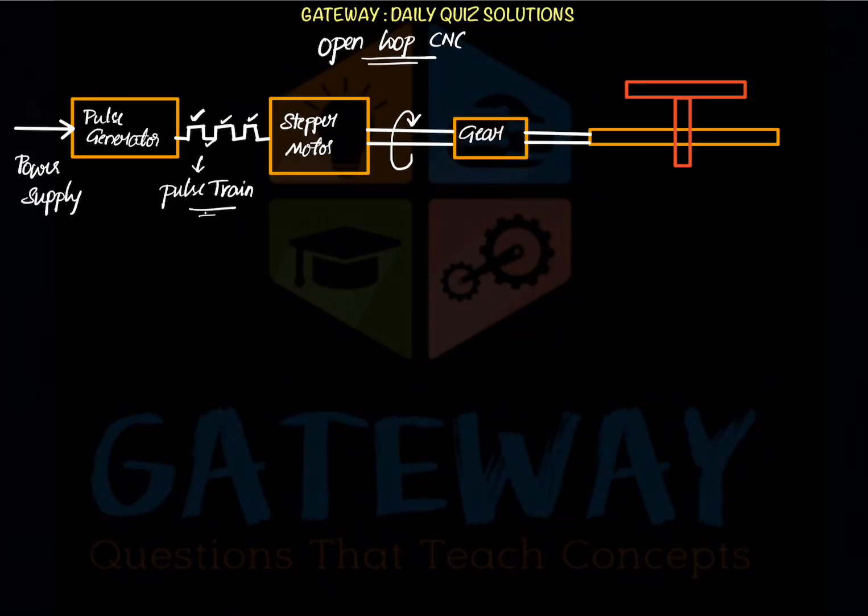And here we will be using a gearbox to control the speed, whether we need to increase or decrease, as we just discussed. This gearbox will be giving power to the lead screw. This is the lead screw. It has screw threads here. This is the lead screw, and this is called the table on which we place our workpiece. We know the screw will have some pitch. Since it is a lead screw, generally a single start thread is used.